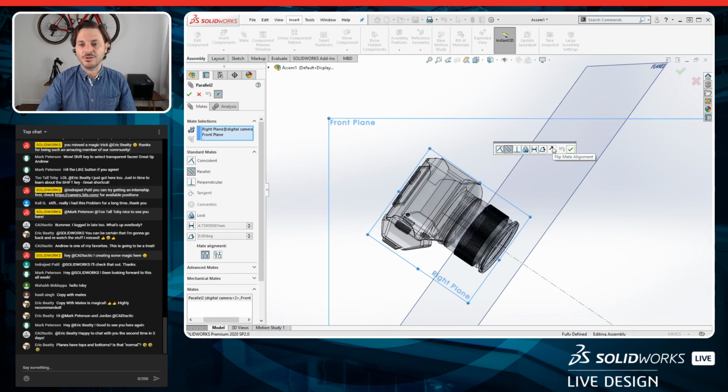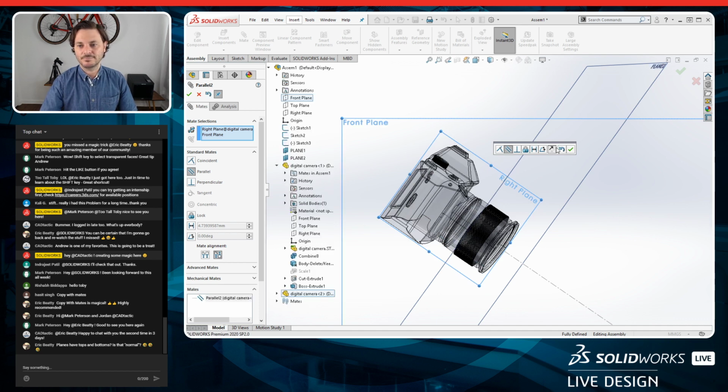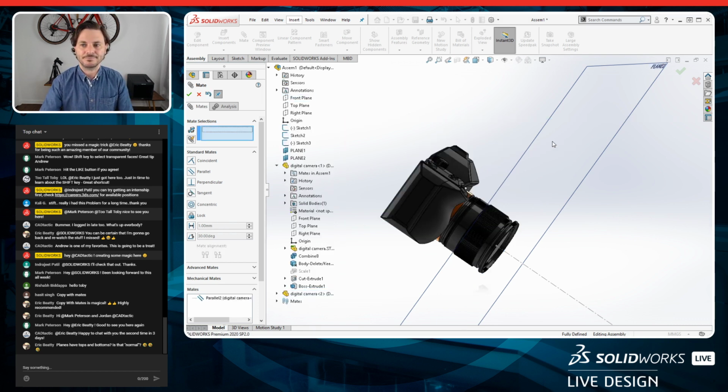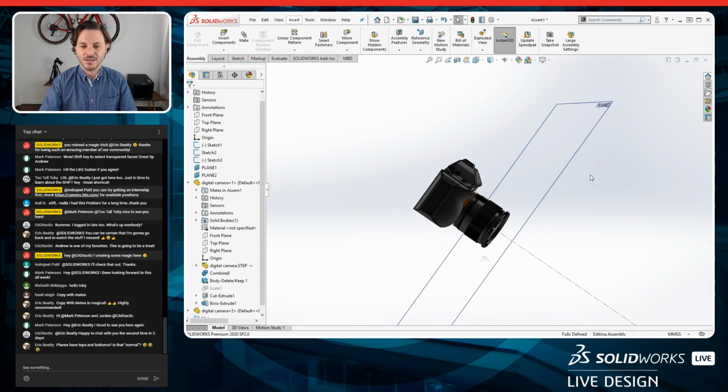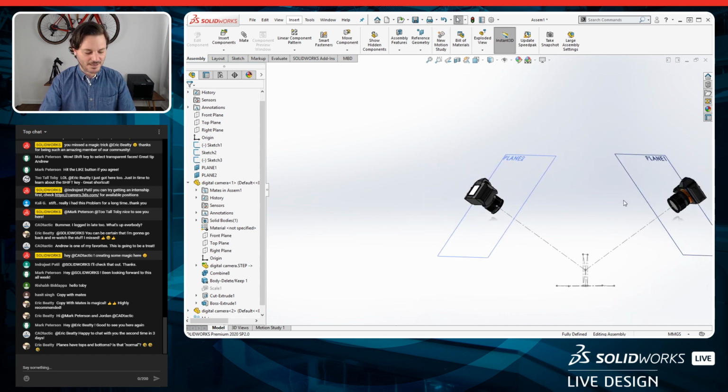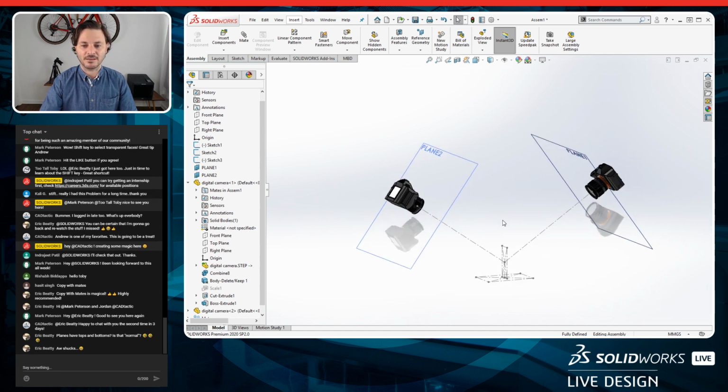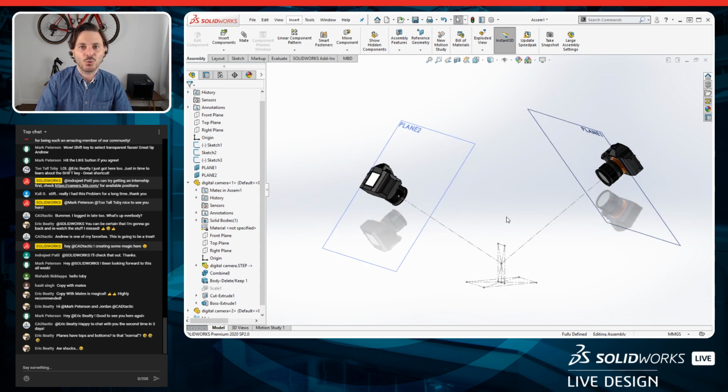And all I want to do is flip the mate alignment. Boom. And done. So that's really all I had to do, just flip that mate alignment. That was a big discussion for just flipping mate alignments. But hopefully you guys saw a little something cool using breadcrumbs.